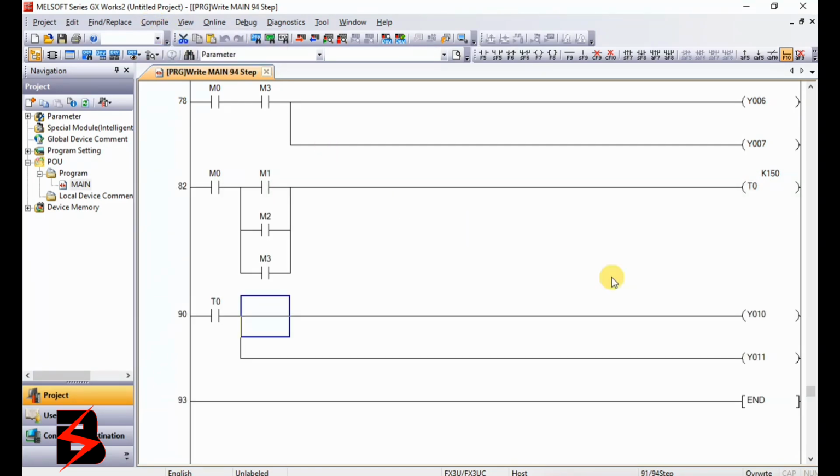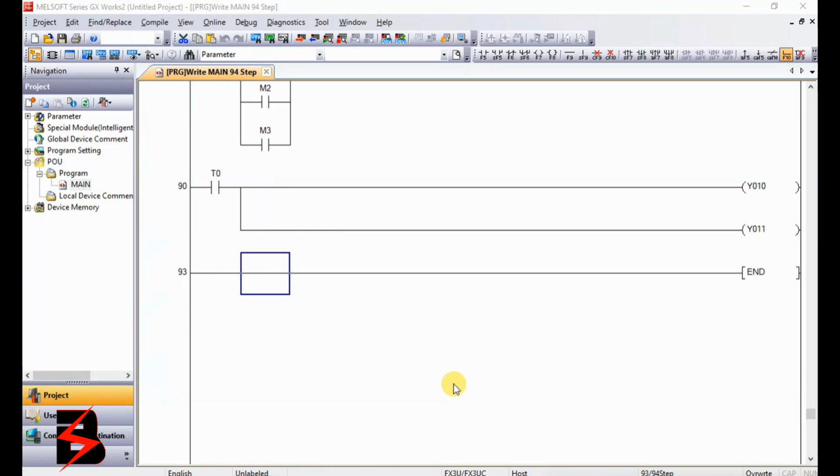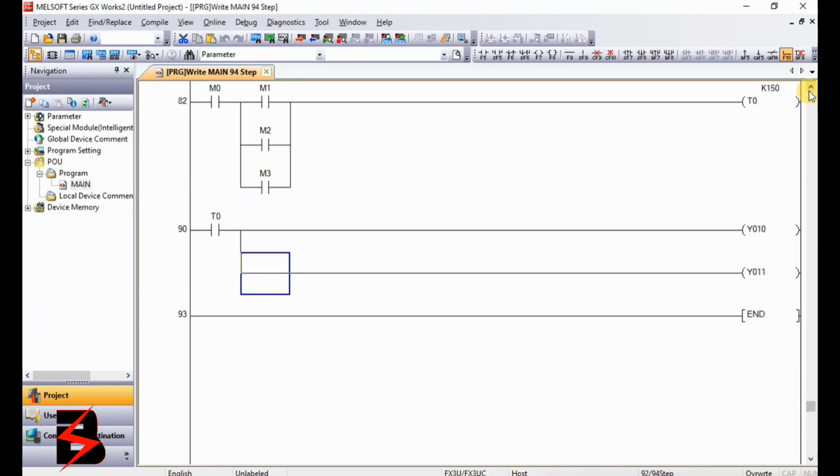I think we are done with the ladder logic. Let me first go through and see. Hope it is okay. Now this warning, the alarm logic I've put in is that when there are times a blue object can go away, then the sorter fails to go back in the normal position. Like a blue can be sorted, the sorter turns but fails to go back, and yet the system has to start. That means the system is going to remain stopped. That means the alarm is going to be initiated. You are going to see how it's going to happen. So here I think the thing is okay.